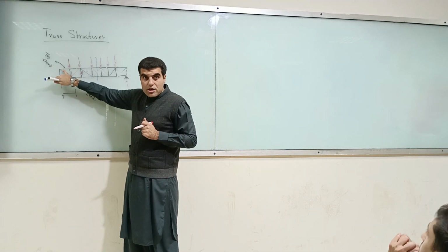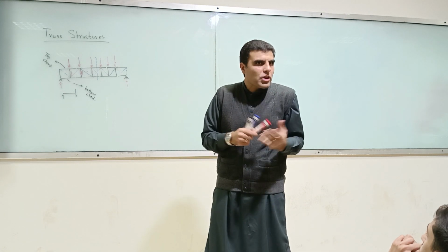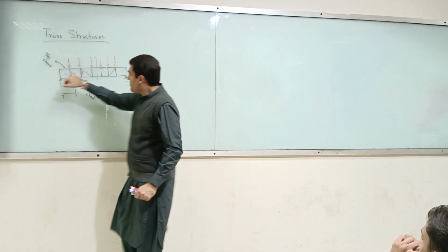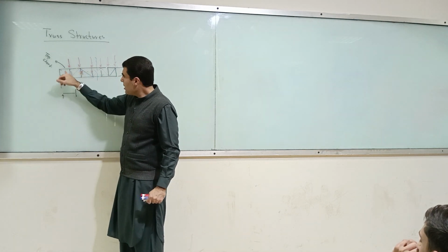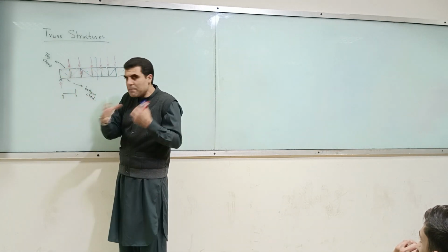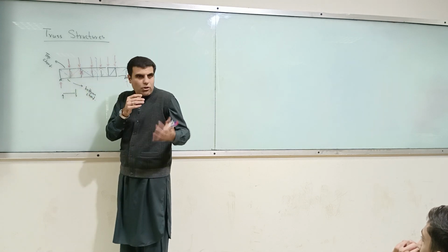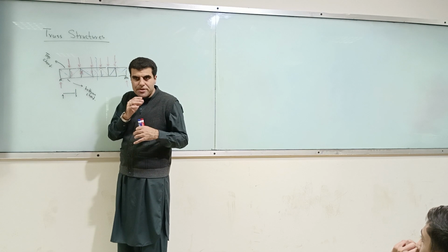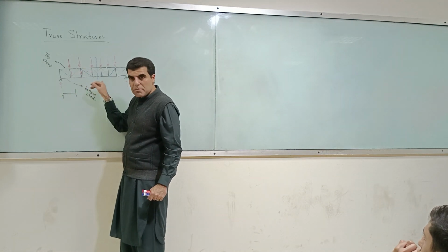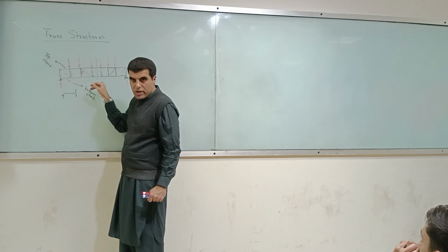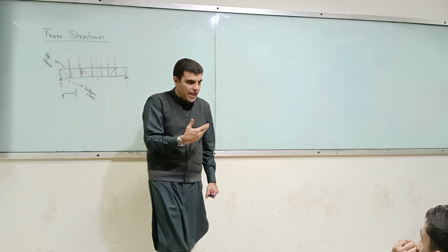Okay? So I would request you that you do this sort of sense check. This is called a sense check. So first of all you work it out. Then you see all the top forces. If you can make sense out of it, if the top forces are positive or negative, or in other words, are they in compression or tension? Then see all these members whether they are in compression or tension. If they are coming out to be in tension under this loading condition, obviously you have made some mistake.